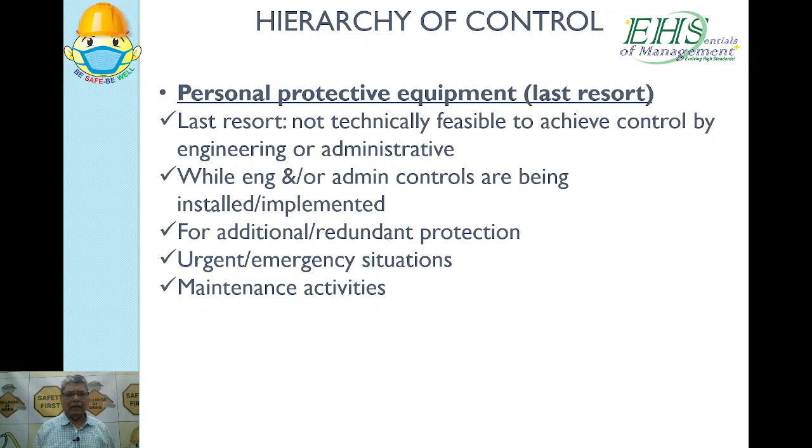If you want additional protection, even when you have the engineering and administrative controls, in urgent and emergency situations and maintenance activity. So every area they define the mandatory PPE, and people working in that area are supposed to use that mandatory PPE.